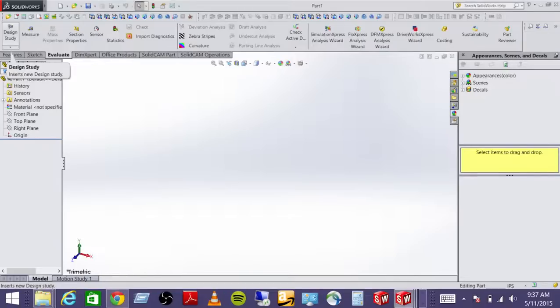You remember in high school, your high school teacher said, hey, just because the calculator pumped out a number, you need to check it to make sure it's the right order of magnitude or it's in the right ballpark for the question that's being asked. Same thing here. So be careful with these tools. Check them. If you use thermal or structural modeling or FEM analysis within SolidWorks or fluids analysis within SolidWorks, make sure you check it against your analytical tools that you're learning in school right now. That's just a life lesson that I bet you're going to bump up to within your college career. So I've warned you, fair warning.